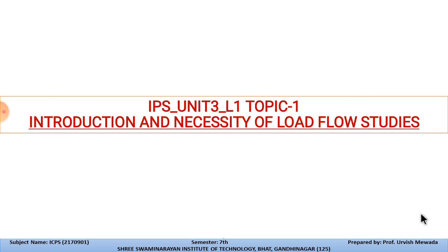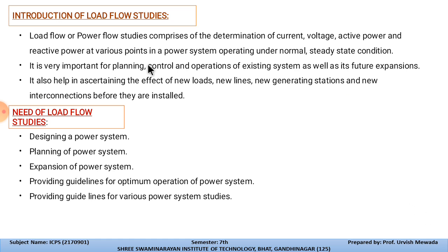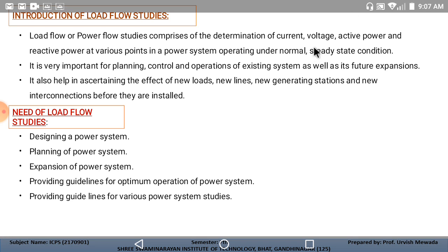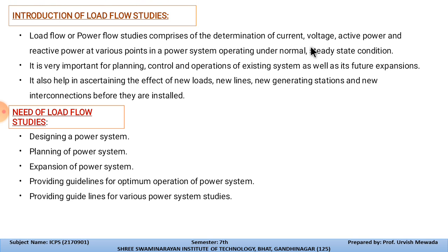Let us start with the first topic, the introduction of load flow studies. Basically, load flow, or power flow studies, comprises the determination of current, voltage, active power, and reactive power at various points in a power system operating under normal and steady state conditions. As I discussed, when we transfer power from the sending end to the receiving end, power consists of current and voltage, and we have three different powers: active power, reactive power, and the combination of these two, the apparent power.